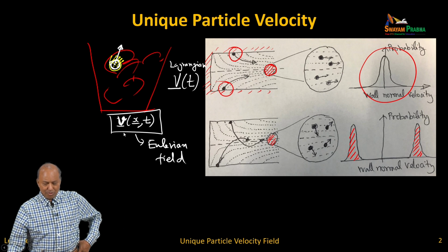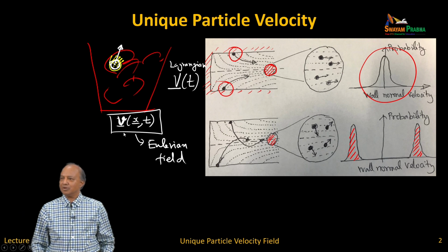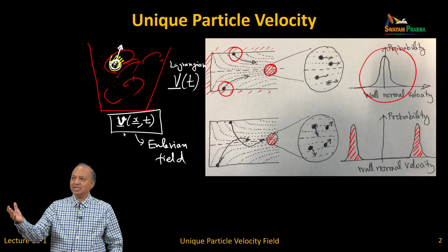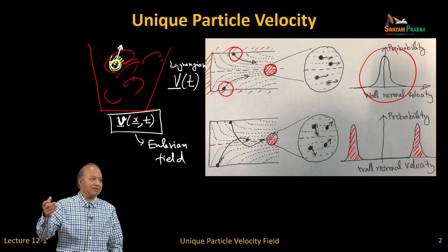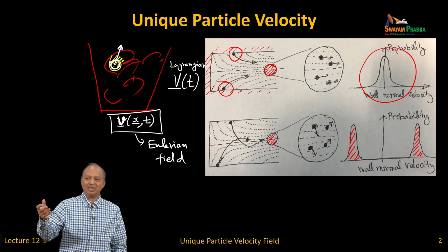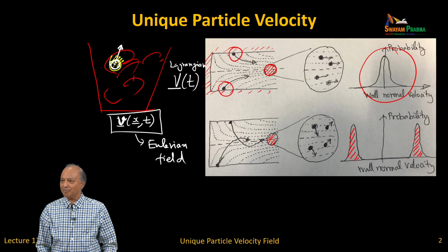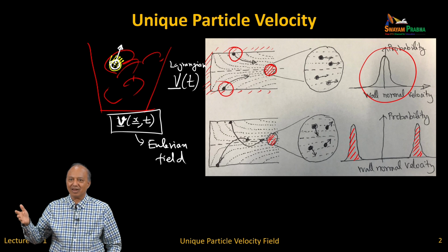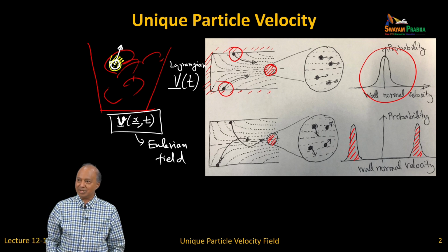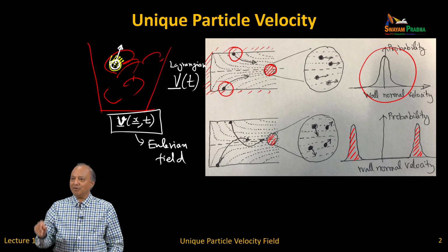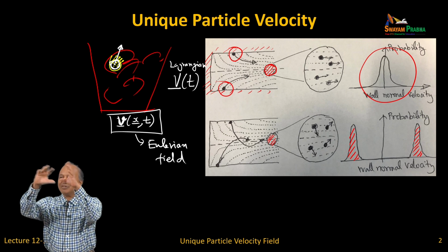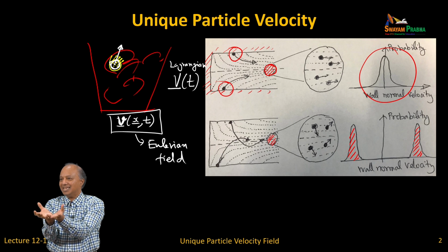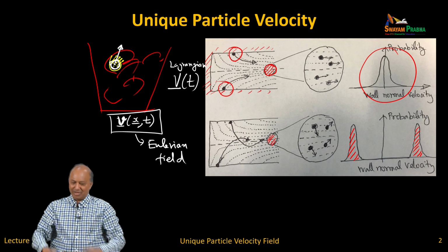But when you do the averaging that we talked about in the last 15 minutes, you change that ith particle's velocity, Lagrangian information, to an Eulerian information. In other words, you can pick any point and ask what is the particle velocity field at that point. What you get out of it is nothing but the average velocity of all the particles that happen to be in a length scale L. Okay.